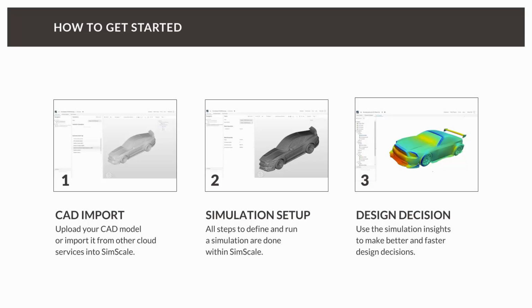Frankie wants to know if we need to define the wind tunnel online or should we mate it in the CAD model. No, Frankie, there is no need to define the wind tunnel in your CAD model. You can just define it within SimScale. All right, I see we have some more questions, but let's collect them and proceed with the presentation, and then we can discuss them during the Q&A.